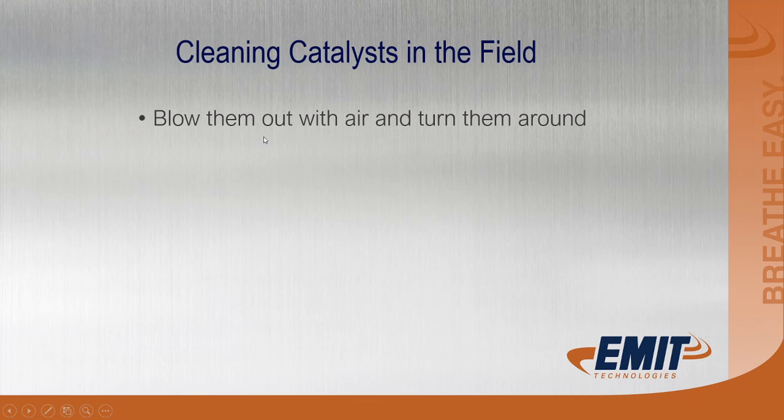If you've got a green hue to your catalyst and you've lost a cylinder or you lost a turbo and you pushed a bunch of antifreeze into the exhaust, you always want to make sure that you run that engine a while before you put a new catalyst element in. If you have a bunch of antifreeze and things that need to burn out of the exhaust after an engine failure, make sure you run it for a while before you put the new catalyst element in.